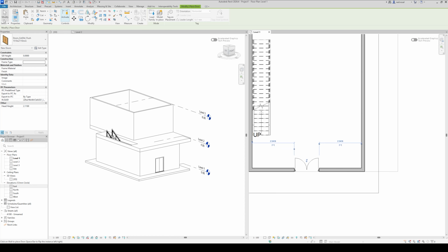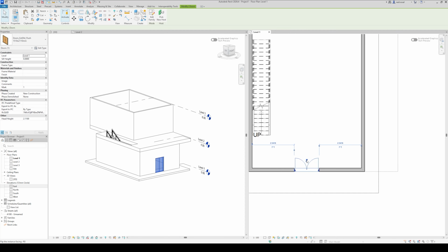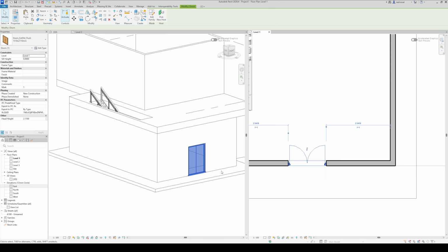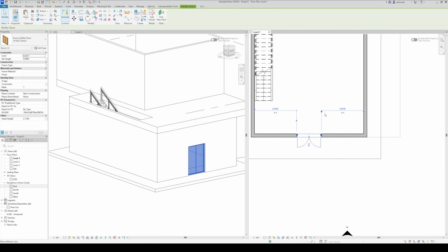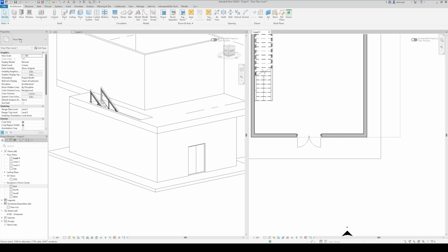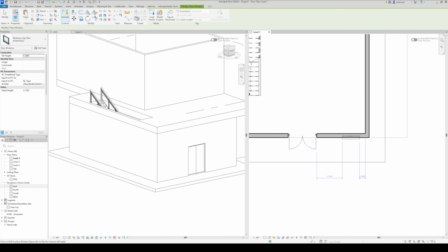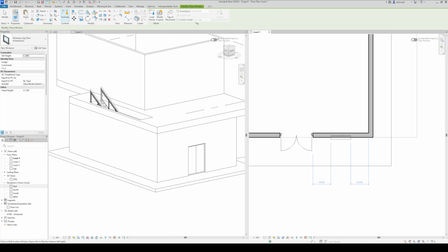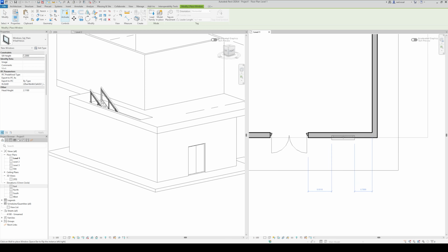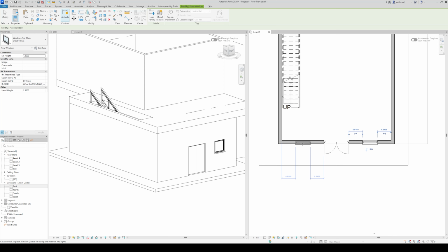I can sort of flip the orientation of my doors as well. Do I want it this way, that way? Up to you. I'm also going to add some windows. It's always going to refer to the center line where the window peaks. So I always want it to go outside, so that it appears like it's poking outside the center line. My bad, forgot to mention.